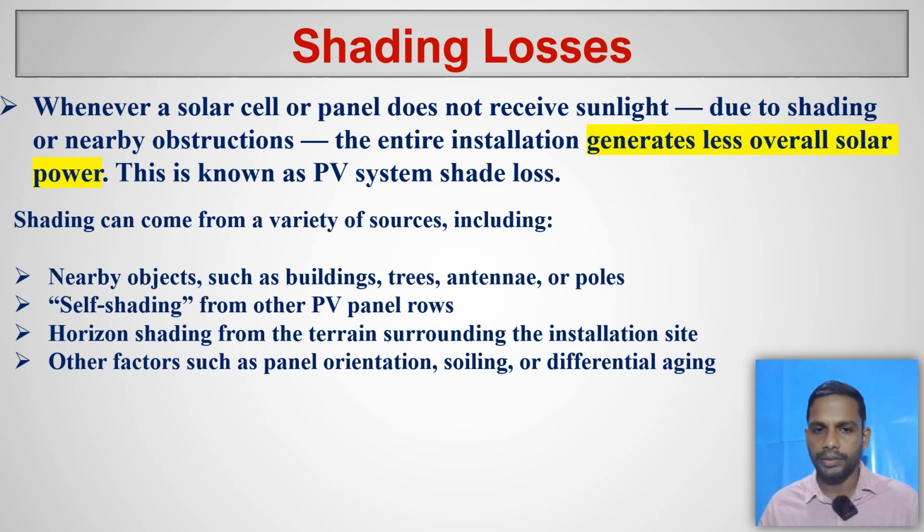So many people do not know this fact: shading of a small area will have a huge impact on the entire system. Self shading is another phenomenon, because of your panel, your mounting rack and all sorts of things. These are all mis-planning or installation mistakes.